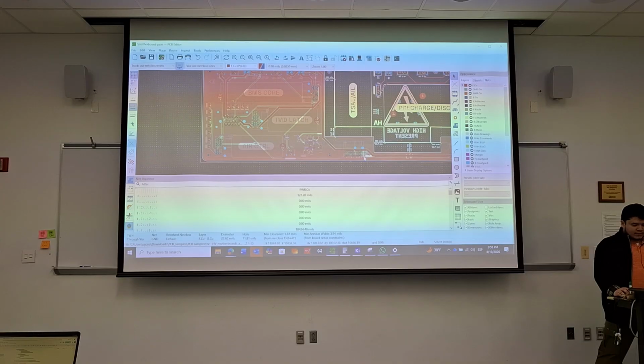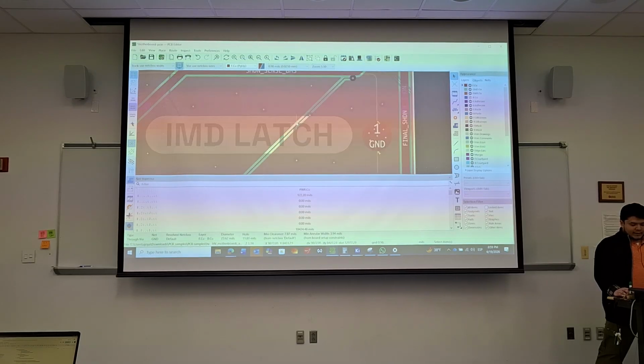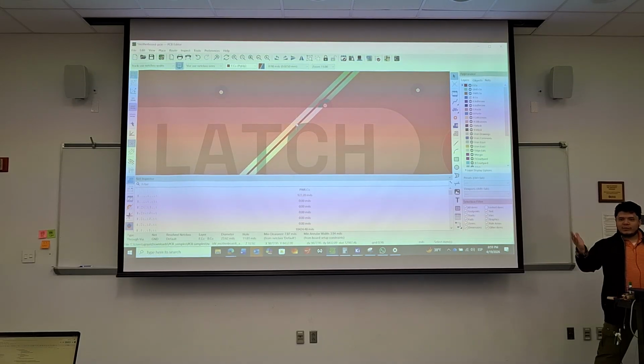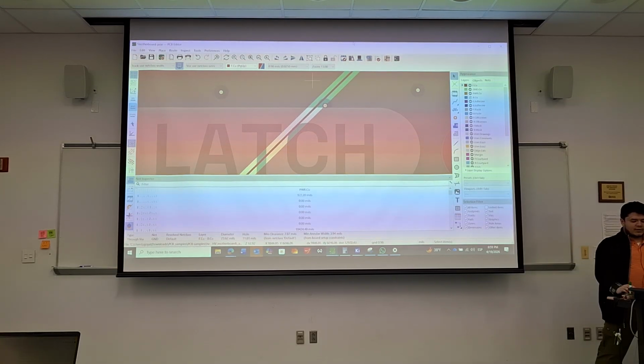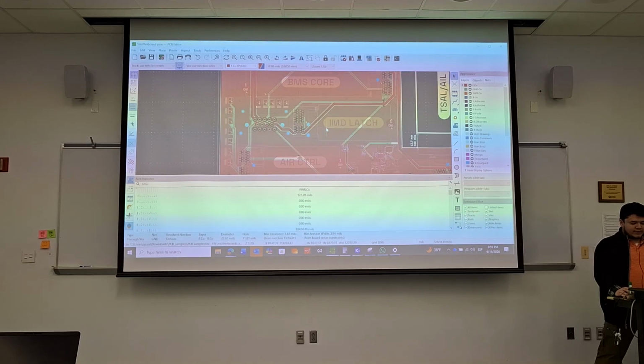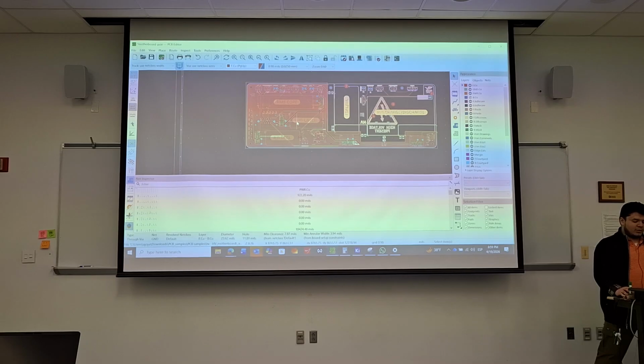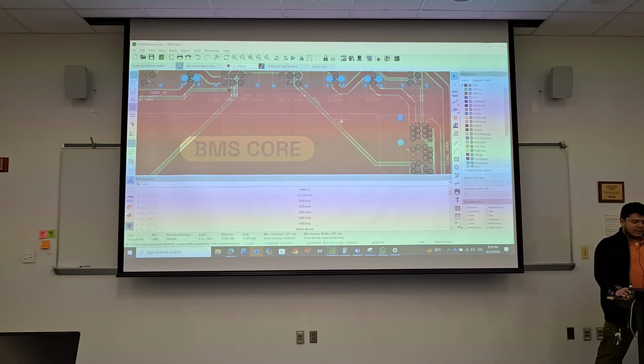Yeah, so the problem is this board is running very long traces, and if it doesn't have any impedance control, because I see differential pairs and everything, but if these were not checked for all the things that we said, you just basically have huge inductors. Because we just saw this CAN bus that is 20 inches long. That has a lot of parasitic inductance, because that is a huge trace. And so all of these huge traces, they're all doing that. And so you just basically have a huge loop or a huge inductor with this huge board. And so I would say that's probably it.